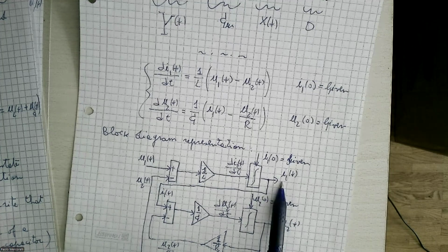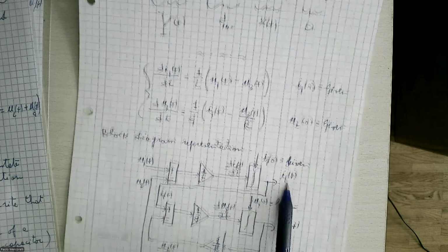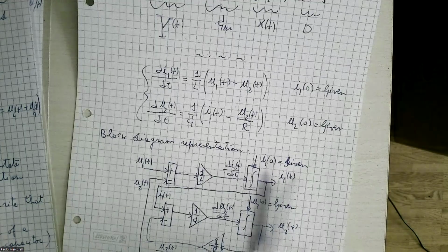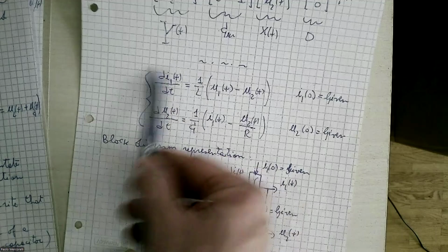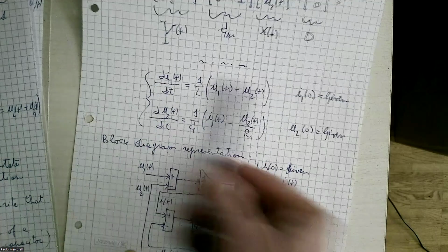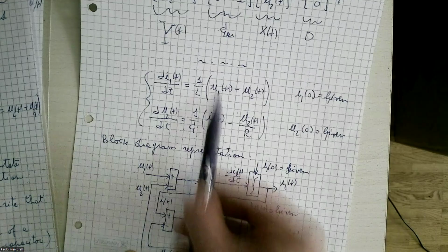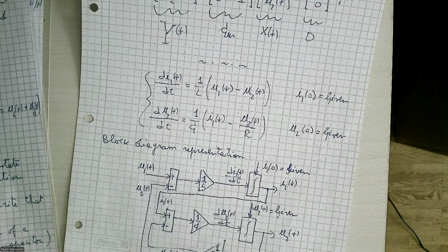From here. If you look at the first equation, it's easy to perform the rest, because between I1 and the derivative again, as before, we have an integral, and you have to consider the initial condition. If I divide by 1 divided L, again as last time, you have this expression, in our case 1 divided L multiplied by this is exactly the derivative. This means this signal here reflects U1 minus U2. U1 is our input, which is the output of the controller.